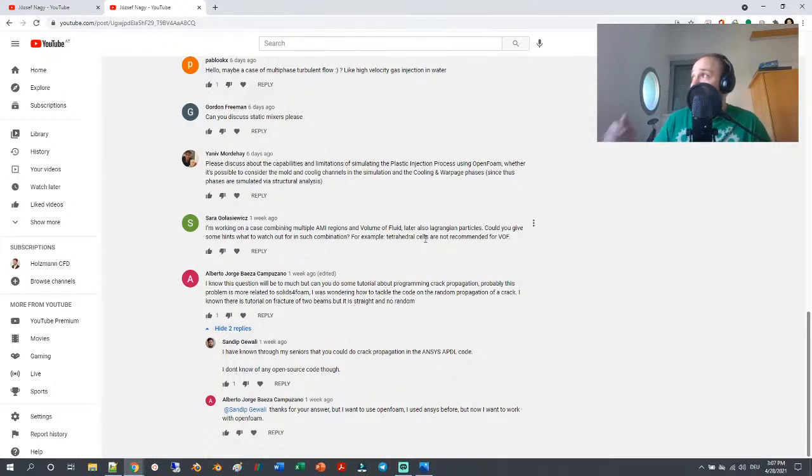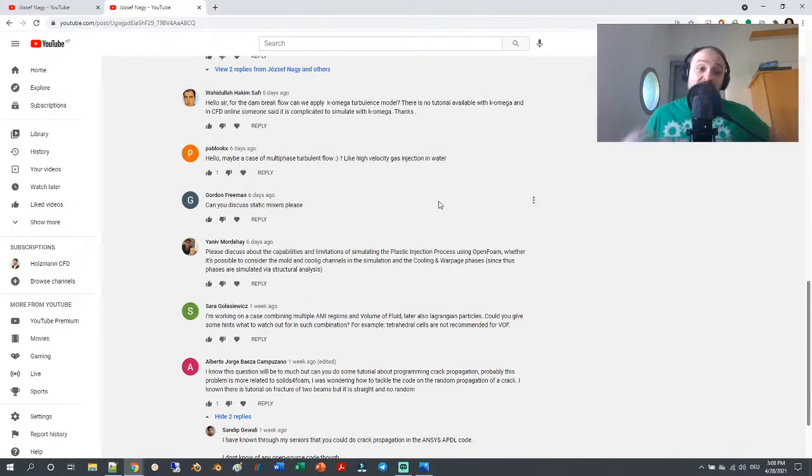So yeah, I personally would advise you to start with one AMI region and rotate only your fluid without any gas in it, then add a second and third into only your fluid without any free surface. And then once you have all your AMIs in your region and they are rotating in the liquid, then you can add your gas phase. And once you have your AMIs with volume of fluid, gas and liquid, then you can go to Lagrangian particles. So this is my opinion on how to do this. So how I would do it.